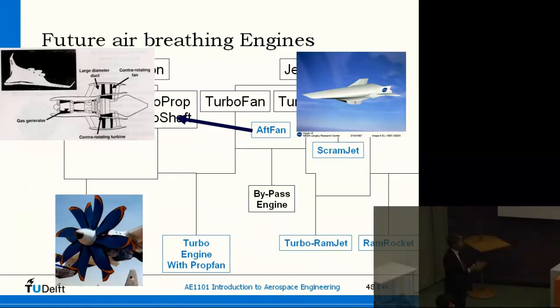Similarly for a ramjet, the air is compressed and reduced in speed, but with a scramjet, we want to keep the flow supersonic in the engine, and scramjet stands for supersonic combustion ramjet. So for high speeds, you can use the scramjet, but clearly not for lower speeds. So the trick is often how to combine getting to the high speed and actually flying at the high speed.